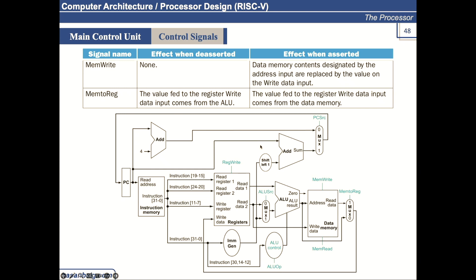The current PC address and the offset value in the branch instruction are added together and the new PC is updated here. So PC source will decide whether to execute the next instruction in sequence or the branch instruction. Any other question?